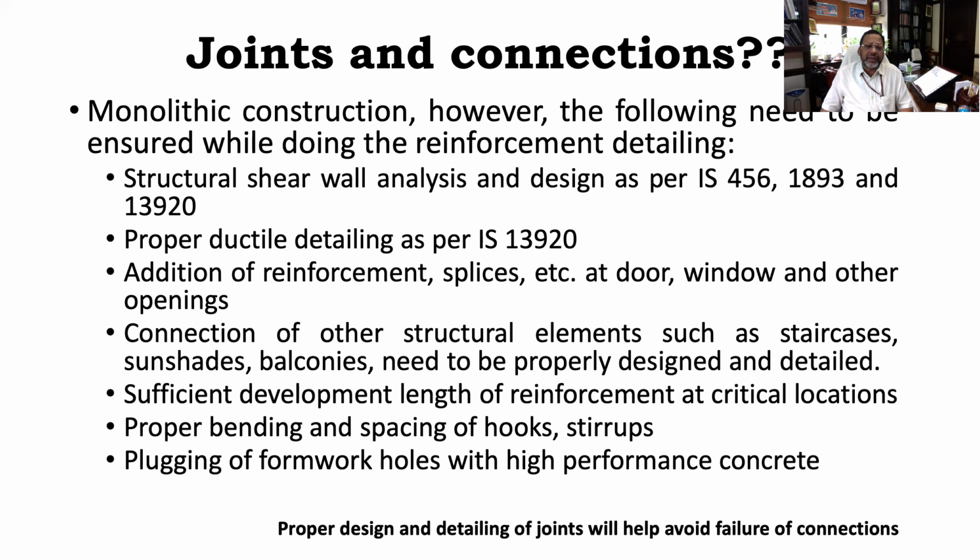So proper ductile detailing of shear wall is very important to achieve monolithic construction. Ductile detailing means the spacing between the reinforcement, the kind of stirrups, the splices, the development length, and other things. And whenever we do monolithic construction using aluminum formwork or this kind of tunnel formwork, always remember wherever you have openings, you have to provide additional reinforcement as per the detailing, at doors, windows, and other openings.